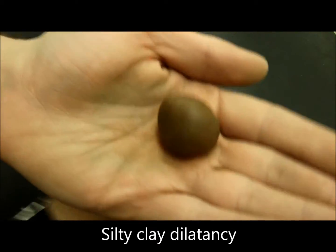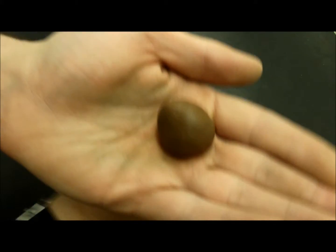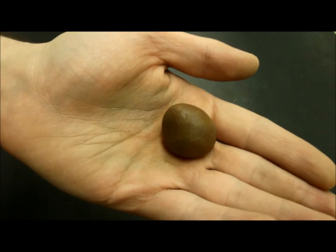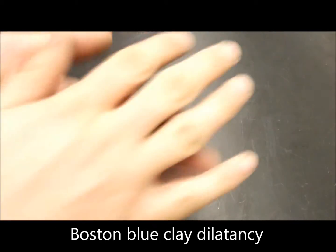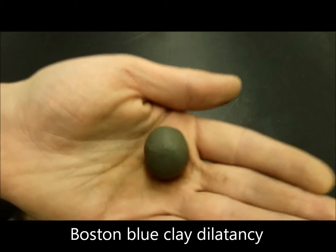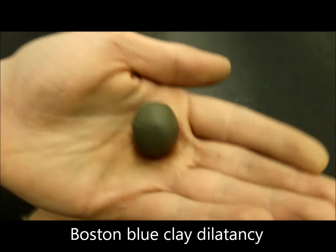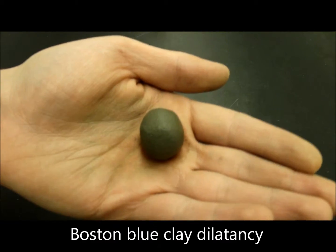Cupping the sample in your hand, tap the bottom of your hand with your other fist several times and watch for water potentially rising to the surface of the ball. Next, squeeze the ball of soil and again, classify the reaction you see. The appearance of water can be described as none, slow, or rapid.